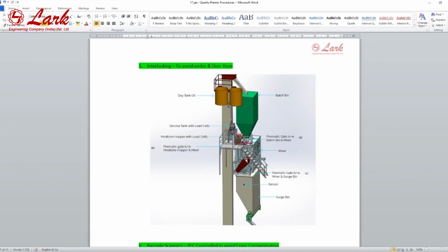So this is a very important part. We have to check this interlocking sequence of dry and wet in automatic feed mills, but we have to make the technicians and feed mill operators aware in manual projects where there is no automation. They should be aware that they have to add the medicines, and after the dry cycle of 2 minutes we have to add the oil.